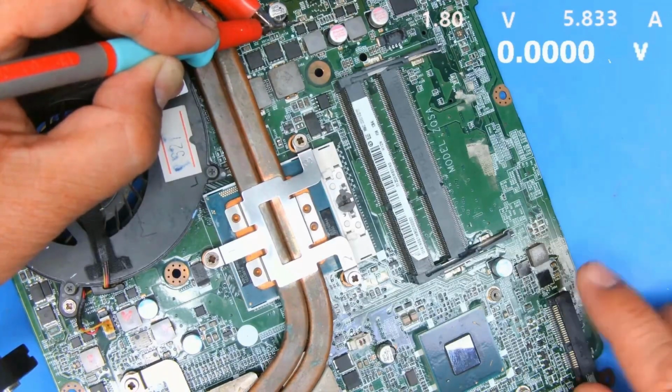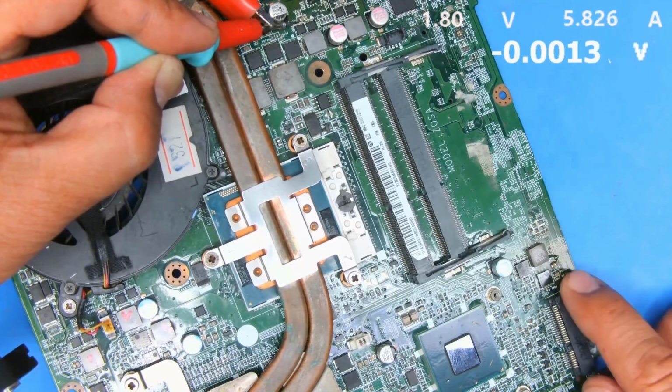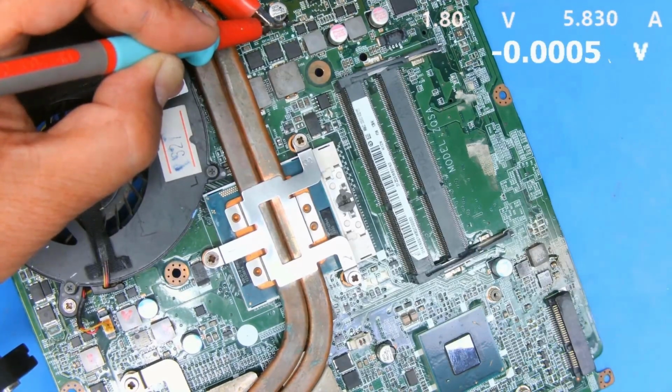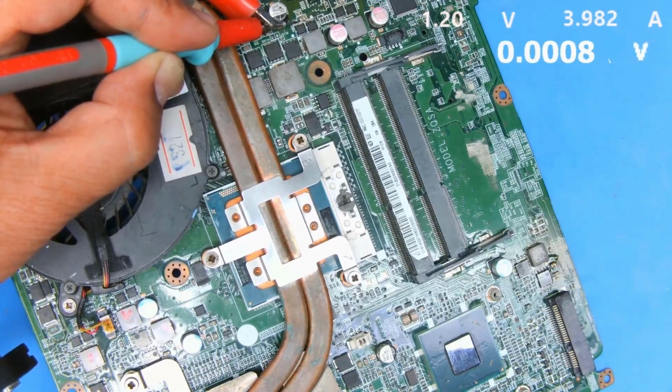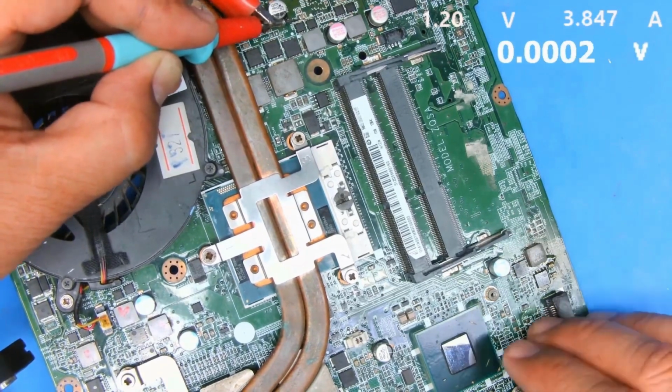Actually, with real heat, just 3 amps is enough for the infrared camera to detect it. It can already find the problem, but this is way too high. Normally, about 1 volt to about 1.2 volts is enough for the infrared camera to detect it. That allows us to eventually find the faulty component. Now, once we found the faulty part, what do we do next?